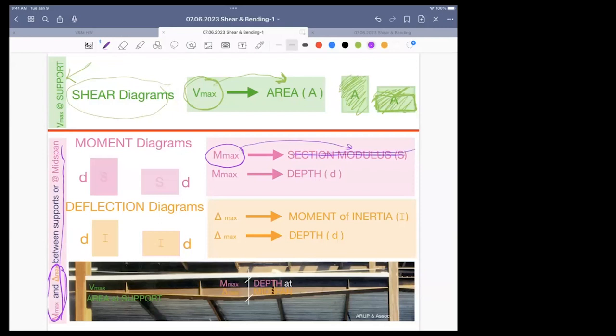All of you hate that. I know, I've been teaching long enough. Who knows what that is? It is the depth. So it says a 2x6 is better in taking load than a 6x2. That's what section modulus is. So the more depth you have, the better you will be in bending, in resisting bending moment.